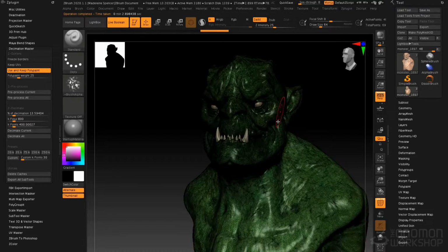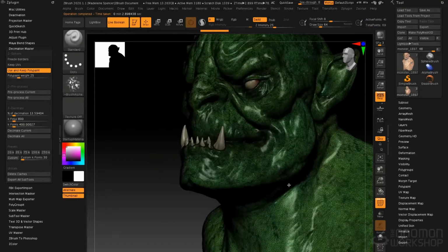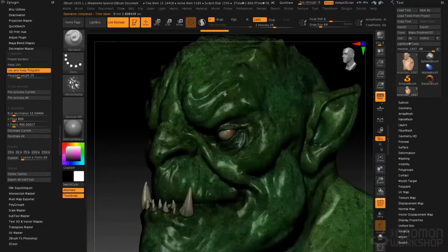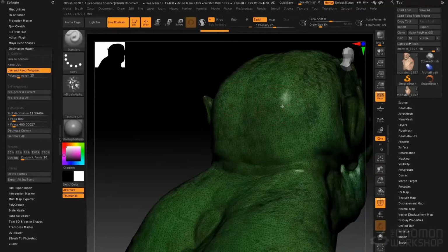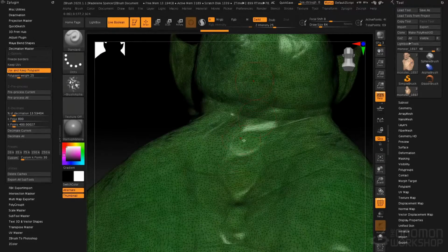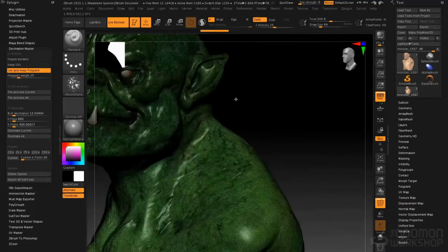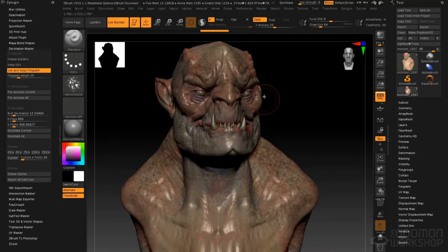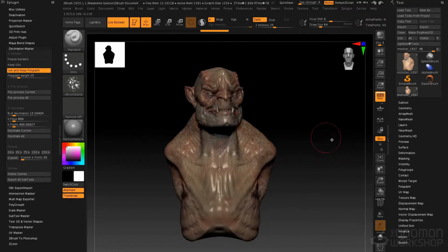If we go into frame mode, you can see what it's done is it has triangulated the mesh. Areas with high detail get smaller triangles, but if we look at the back of the head, we get much larger triangles because there's not as much detail back here. That is the crux of decimation. It basically triangulates the mesh and then reduces triangles in areas that don't have detail and keeps them in areas that do. So now we've reduced this down to a much lower polygon count. It is much easier for us to 3D print this.